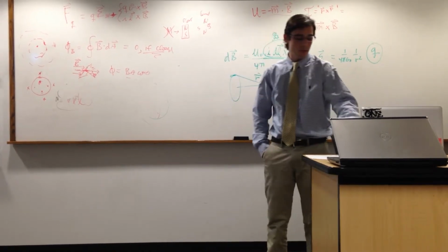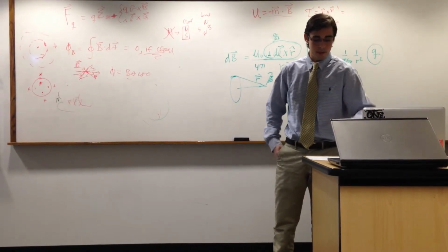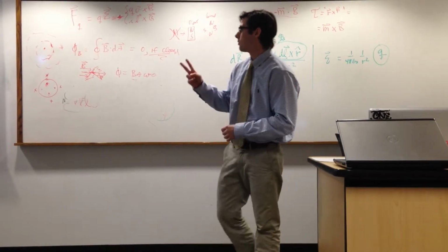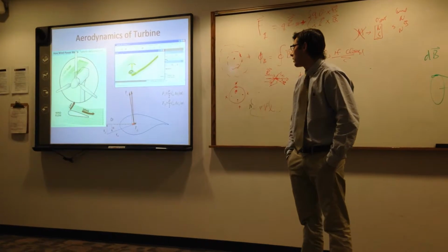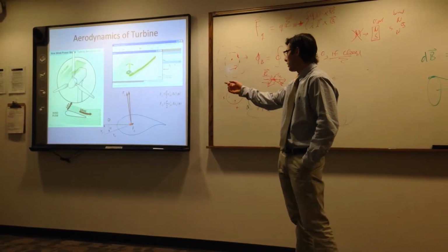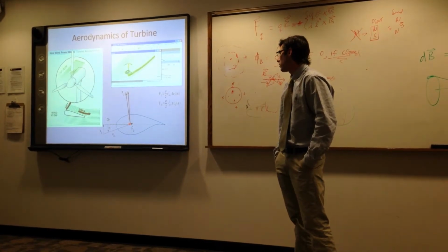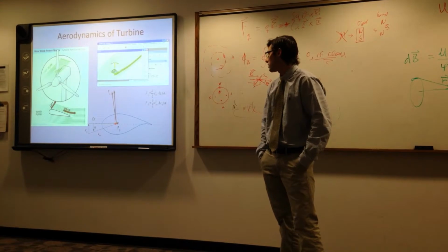in your generator. In the picture up here, you can see, like others have talked about, it depends on 2 equations, your drag and your lift. And like people said before, the formulas are basically the same. It's your rho, which is the density of the air, over 2 times your velocity squared.